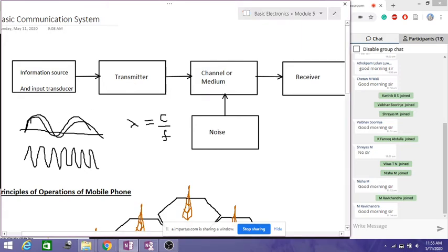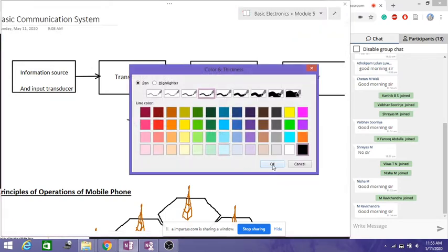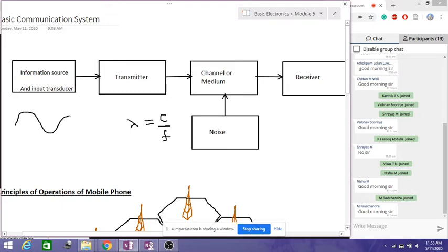Now the same thing, if I sample this signal, for example, let me erase this and write this signal here. If I have the same analog signal here, rather than transmitting the entire analog signal, I do sampling and convert these values to digital form. These digital values I can modulate again. For example, I have sampled this entire signal here. After sampling, I obtain the codes, and by using some kind of waveforms, I can do binary modulation, that is binary frequency shift keying or binary amplitude shift keying. This kind of modulation I can perform, and then transmit.